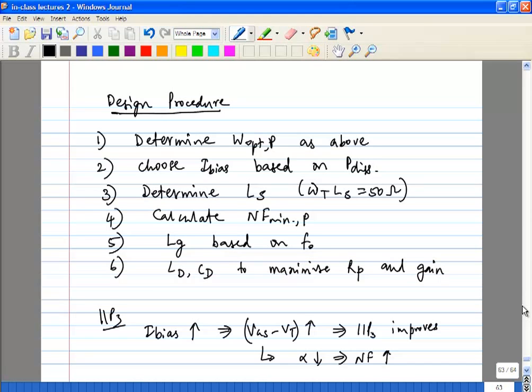It could be as high as like minus 20, minus 10 dBm. Even if you expect a gain of 10 on the LNA, you don't have much requirement on the output swing. It will never go to rail to rail operation. That's right, that's for sure.